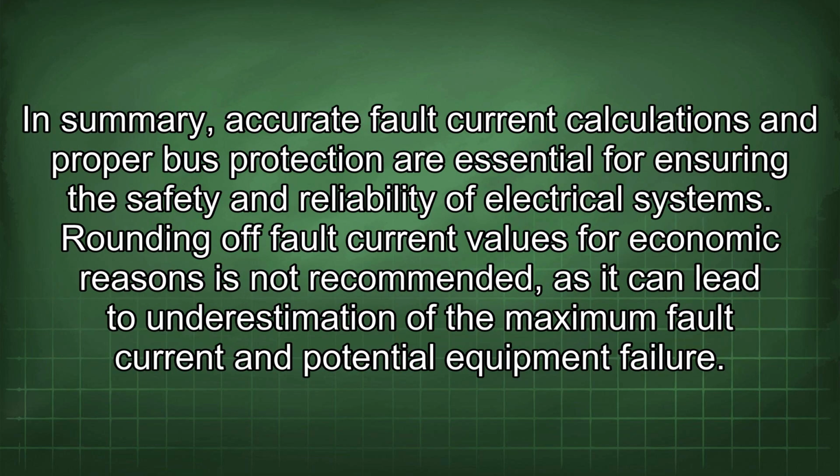In summary, accurate fault current calculations and proper bus protection are essential for ensuring the safety and reliability of electrical systems. Rounding off fault current values for economic reasons is not recommended, as it can lead to underestimation of the maximum fault current and potential equipment failure.